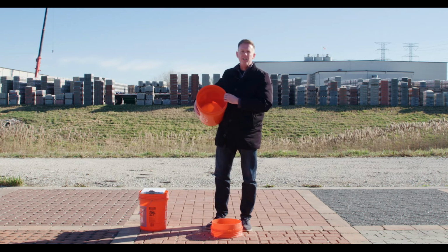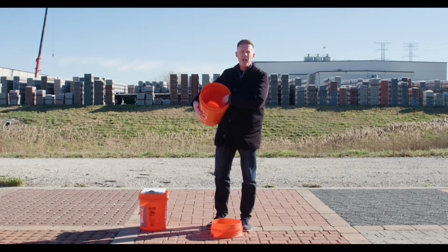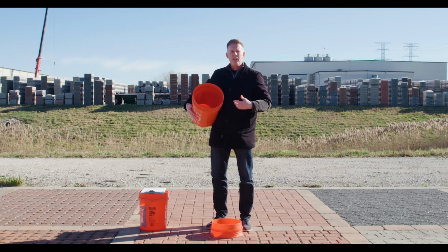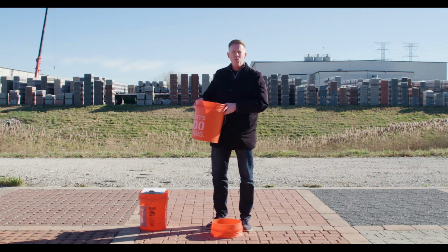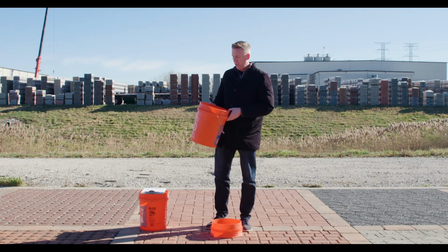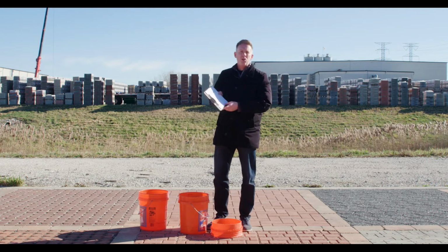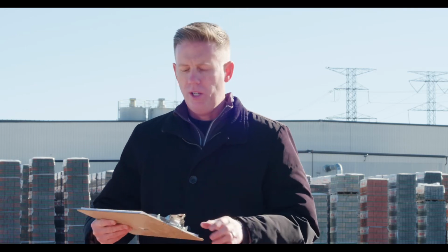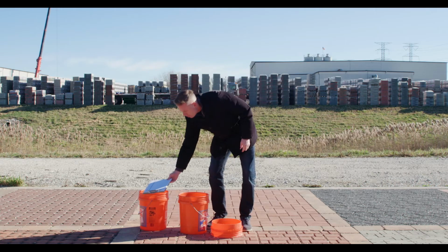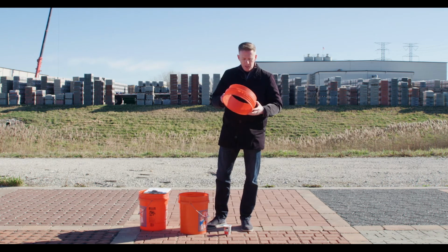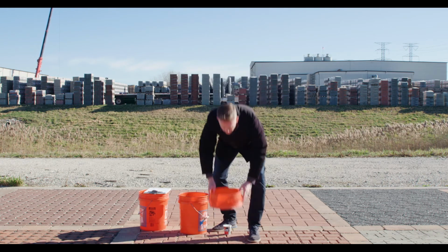Now we've pre-marked this for our 8-pound water line and our 40-pound water line. Makes it a little bit quicker when you're out there in the field trying to do this test, so you don't have to weigh it each time. So we've pre-weighed this area. And the last thing I mentioned is you really need to record this information. So have a piece of paper you can write down the times that it takes to drain this material. So we're first going to start by putting down the ring across the surface and applying our plumber's putty.